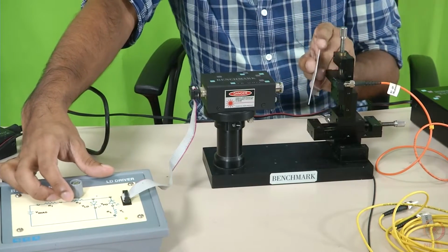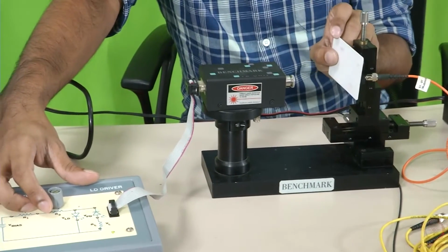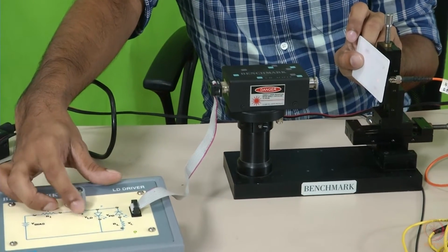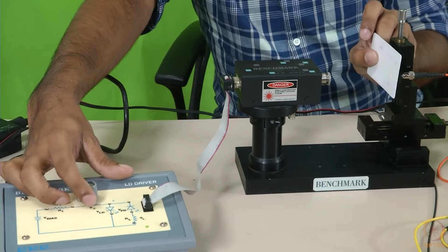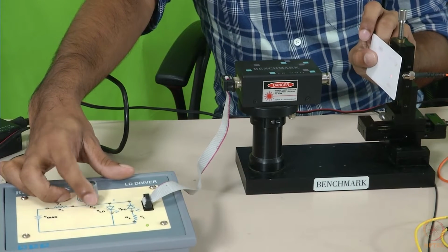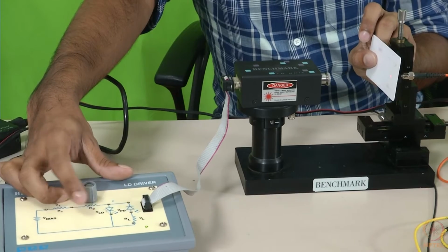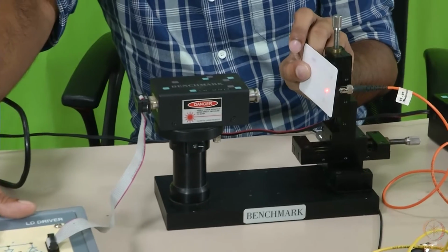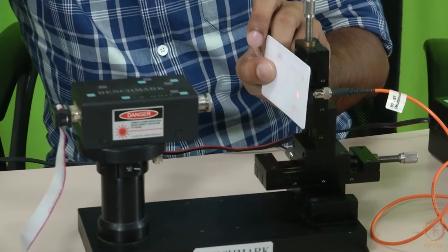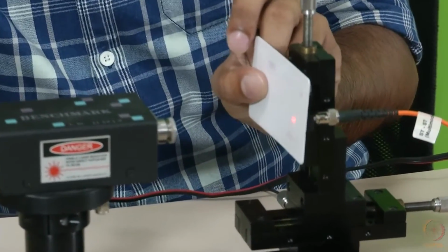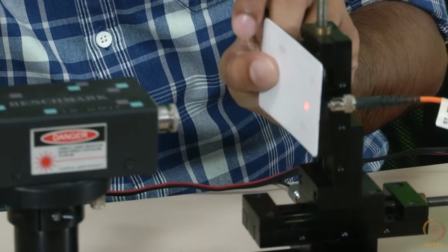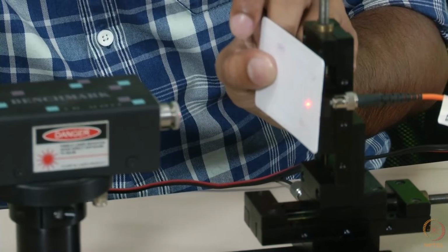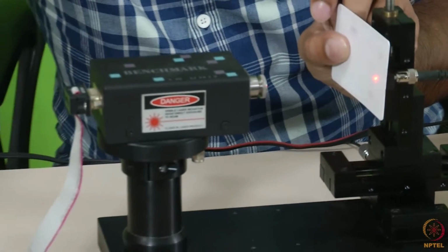As you can see, a small red dot is visible. I don't know whether it is visible for you guys. So a small red dot is visible, and I'm going to increase the current. The laser having turned on, it is still a very small speck there. Now you can see the light is slightly increasing and then suddenly turns on. This is where the threshold is, and the laser has turned on, beyond which I don't have much to rotate here in the multi-turn potentiometer.